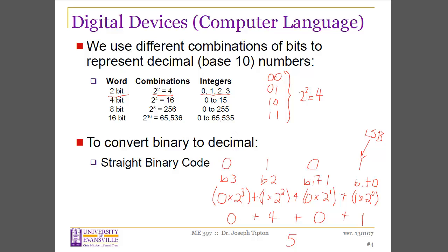And then this one has the most influence on the outcome, so we call it the most significant bit. And as you might realize, the least significant bit then is sort of the resolution at which we're able to store information, the smallest possible increment, which has an impact on our error estimation, uncertainty calculation a little bit later.